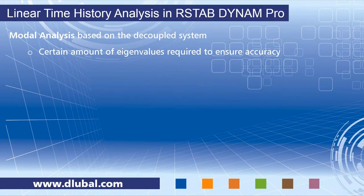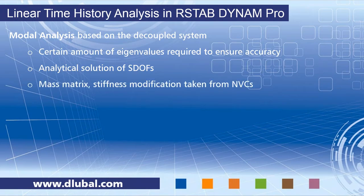And how can you know whether or not you have enough eigenvalues? You can have a look at the effective modal mass factors. And it's also important to compare natural frequencies of your structure and the excitation frequency that you have. Dynam Pro offers an analytical solution of single degree of freedom systems here. So as you find it in the literature, you have closed solutions for periodic excitations and a Duhamel integral for arbitrary excitations. The mass matrix and stiffness modifications are taken from the natural vibration case that you defined and assigned.